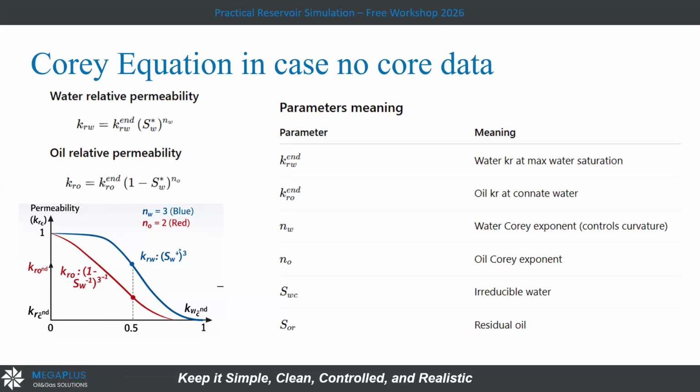In this, the input is some assumptions and the normalized water saturation again, and here is the n. What is the n? If people here have experience, they will know the n is the factor that you multiply to smooth these curves. These curves represent the relative permeability across the saturation of each fluid. So we can depend on Corey. We can do an equation to insert the relative permeability curve, by analogy taking a relative permeability curve from the neighbor field or something.